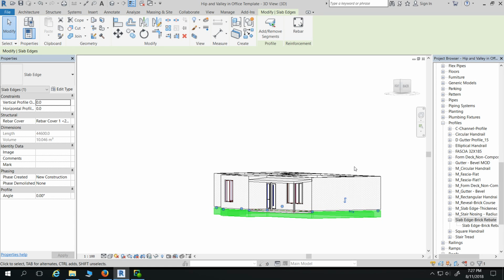There's two ways to bring your brick down. The easy way, and the way that we do it at work because we're really lazy, and I don't necessarily agree with it, is to move the base offset constraint of your wall minus 86, and that will bring the whole wall down 86 mil. So externally it'll look fine. In a section you can just join stuff and it just magically blends in. The other way you can do this